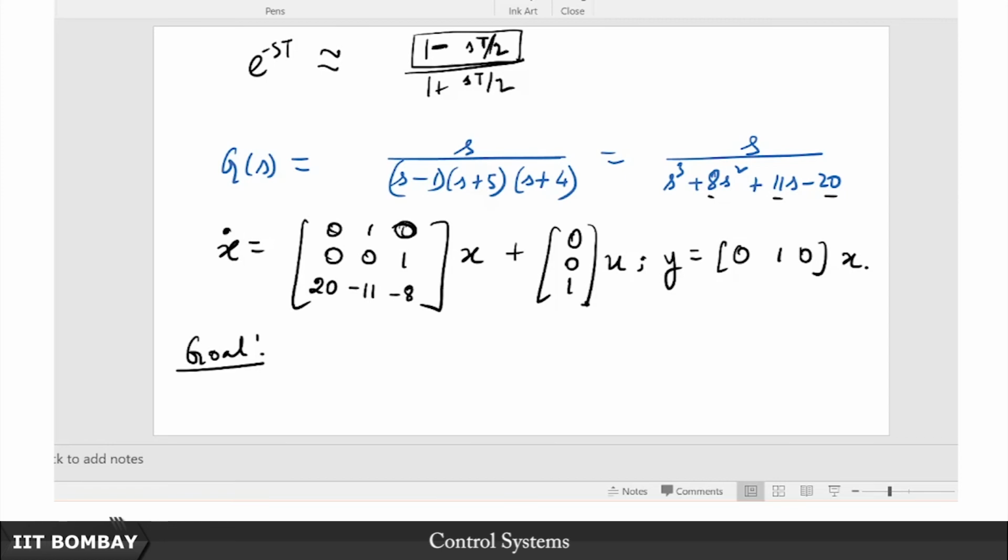If you learn linear quadratic regulator theory, LQR, optimal control, then you will understand that where to place the poles is a critical question that can be answered by the optimization of some cost function. You want to optimize the energy spent, so you put some weight on the amount of control effort you are applying, and you want to put a weight on your state values, you do not want your states to be very far away from the 0 value, or your desired values, so x minus xd. You penalize any deviation of the state from its desired values. So that is how you choose some cost function. Anyway, that is again beyond the purview of this, but this is what we are going to say.